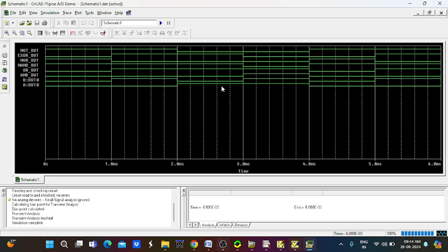And next we move to the next case, 1 0 combination. So A value is equal to 1, B value is equal to 0. So in this case again AND gate is equal to 0. So your output is 1 into 0, 0. OR gate, 1 plus 0, now it is equal to 1. Next NAND gate, 1 into 0, 0. That bar will be 1. So NAND gate output goes logic 1.